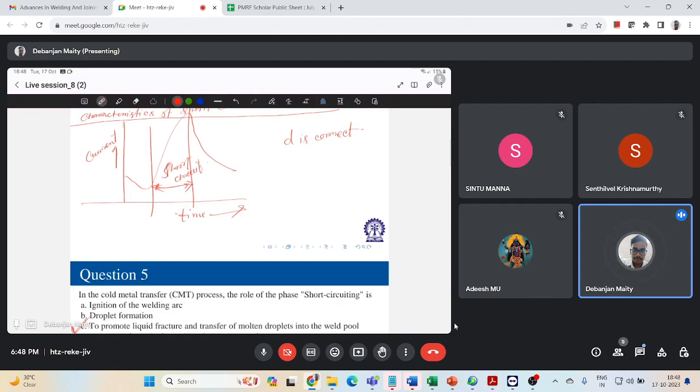In any kind of 3D metal printing, you will have the 3D geometry of the object, right? You will have some CAD design or CAD file. The software in the additive manufacturing machine will slice it into layers. That's how it decides the layer thickness. Then your CAD file will be converted to some .stl format, and all the data will be saved to the 3D printer.